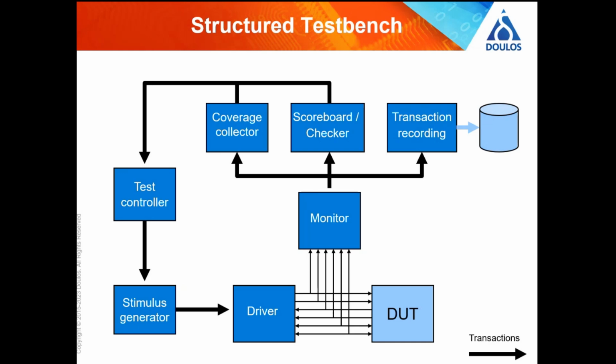So what we mean by a structured test bench is a test bench made out of different pieces, different components, and I don't mean VHDL components, different pieces that have specialist jobs to do. So some of them are more obvious than others on this diagram. So here it says stimulus generator. That's pretty obvious what that does. It generates stimulus, but not as ones and noughts. It's not just waggling the pins on the design under test.